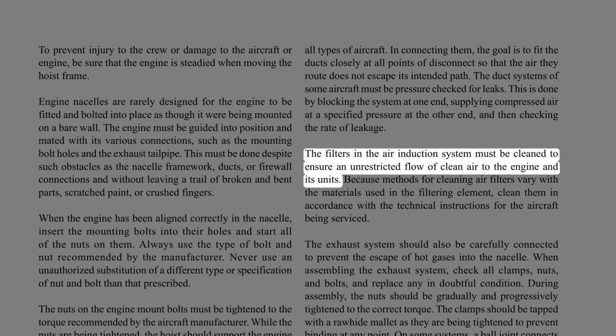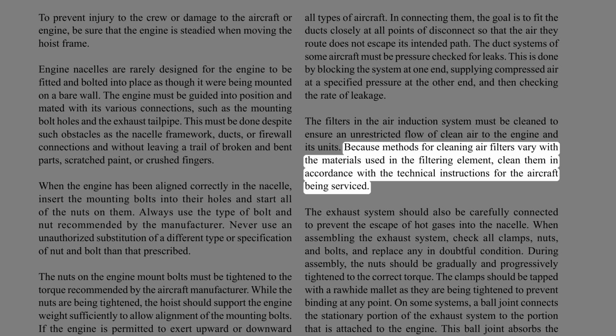The filters in the air induction system must be cleaned to ensure an unrestricted flow of clean air to the engine and its units. Because methods for cleaning air filters vary with the materials used in the filtering element, clean them in accordance with the technical instructions for the aircraft being serviced.